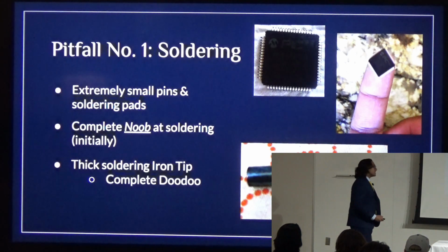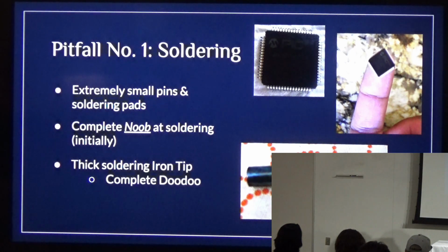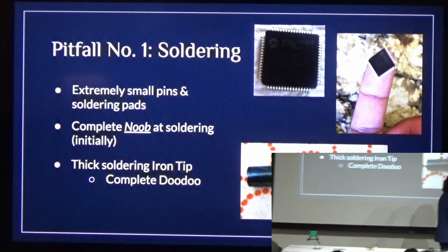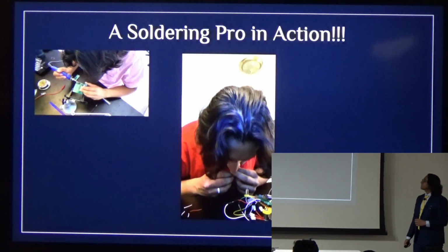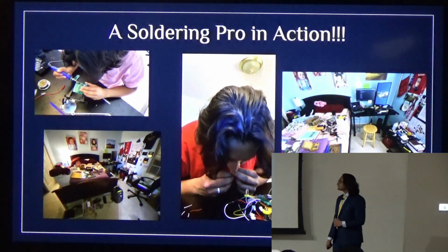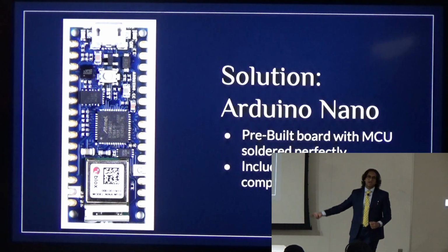So what really happened in the end is when I soldered on the microcontroller for this printed circuit board, I completely fried the chip. One of the connections was bridged, and I passed current where it wasn't supposed to be, and it got ruined. So then I opted to come up with the next solution, which was using the Arduino Nano.